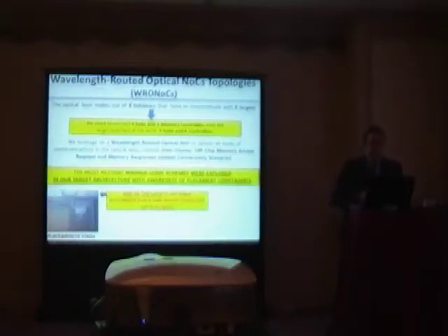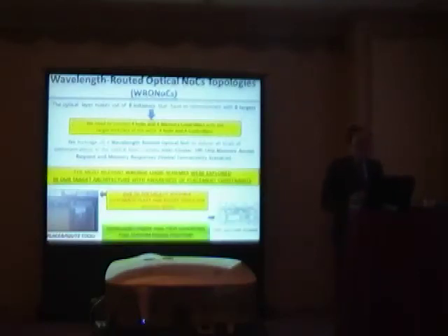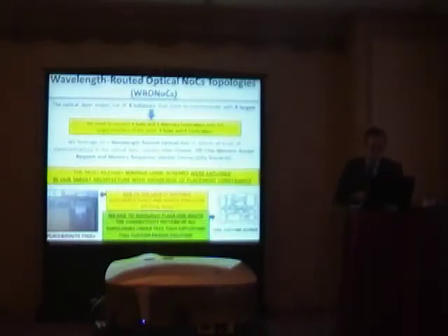Unfortunately, due to the lack of a suitable and good automatic place and route tool for optical NoCs, in our work we had to manually place and route the connectivity pattern of all topologies analyzed, thus using a full custom design solution.